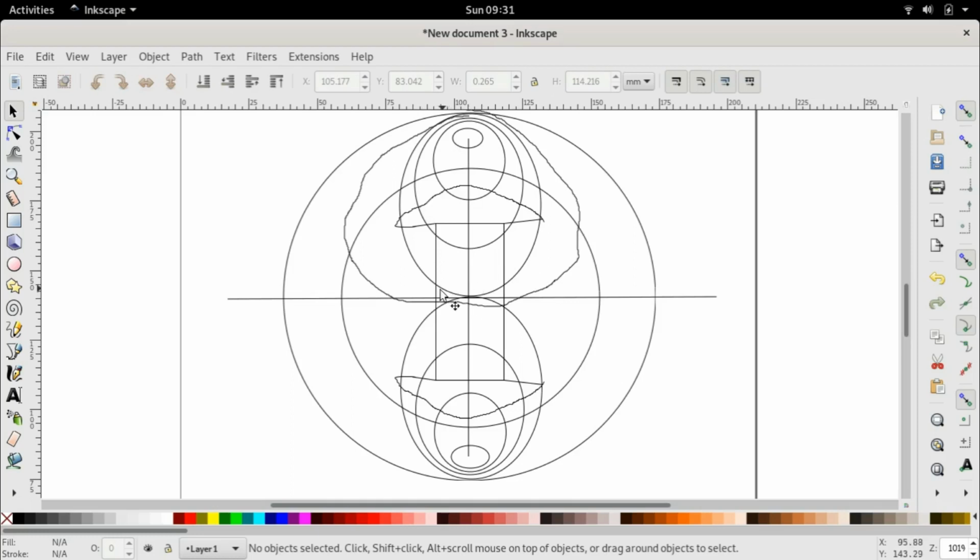In the previous section, the flux paths were able to flow through the entire cross section, this entire midsection rather. Whereas now it cannot flow through the midsection; it can only flow through these salient poles themselves, that is, these few flux lines. These flux lines outside now face a huge air gap, and therefore the reluctance is huge. As a result, the flux is very weak.